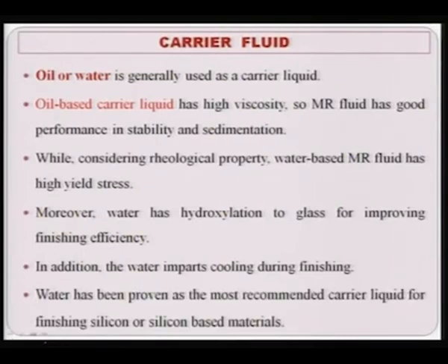Water has been proven as the most recommended carrier liquid for finishing silicon or silicon based materials. Invariably water is used in case of silicon or silicon based materials for finishing purposes, because it chemically reacts and is able to easily finish ceramics or ceramics based materials by comparatively soft abrasive particles.